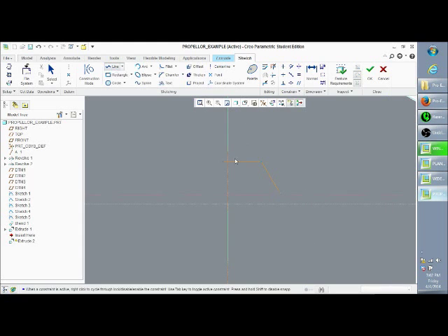So select the line tool again, hit it out, make sure that this point ends up on your center line and locks onto it. You can just make it look however ugly you want because we're going to be going in and fixing it. So it looks like a very off hexagon right now. We want to go in and use the same equal constraint. So select that. Select this top line. Select the side line. Makes those two lines the same dimension. Top line again. Side line. Makes them the same dimension.